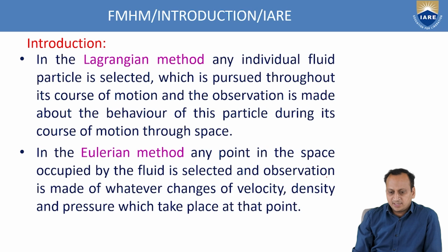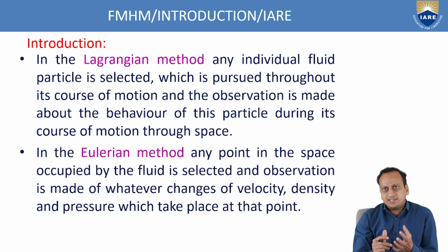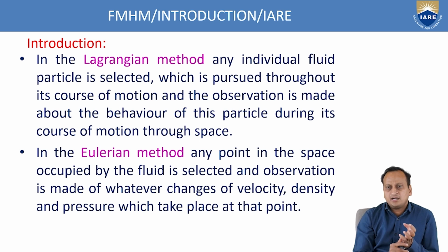In the Lagrangian method, the individual fluid particles will be selected, and they will be traced over a period of time. It is a study with respect to space and with respect to time, to analyze whether and in what way their behavior is going to change. That is the Lagrangian method.